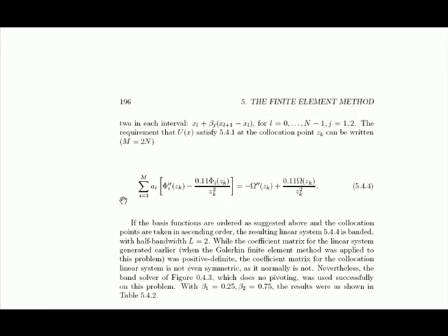And for this example, these are the equations we get. Remember, u is omega plus summation of ai phi, so I've taken the omega in each term off to the right-hand side and left the ai's on the left-hand side. And as with the Galerkin method, you end up with a system of linear equations. Here's the right-hand side, here's bk, and this is aik, or aki. And again, the matrix is going to be sparse if we use the same kind of phi's that we've been using.